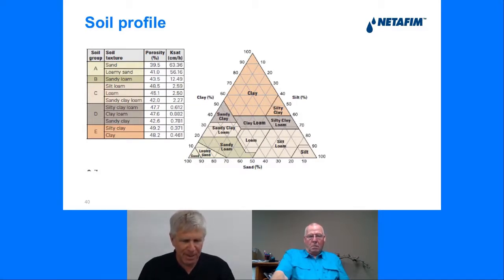The physical properties, I'm speaking about soil texture. What is soil texture? It's when I take a soil sample to the lab, and they separate it into different fractions according to the size of the soil particles. The smaller the soil particle is, the higher the surface area that it has. The smallest are clay particles, which are smaller than 0.002 millimeters. Then there is silt, which is between this and 0.05 millimeters. And the largest are the sand particles, which you can also define as small and big particles.